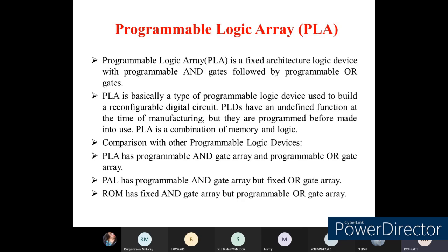Depending upon the input we select, we need to analyze that many combinations of the input. For the 3-bit parity generator, there will be 2 power 3 input combinations, starting from 0 0 0 to 1 1 1.